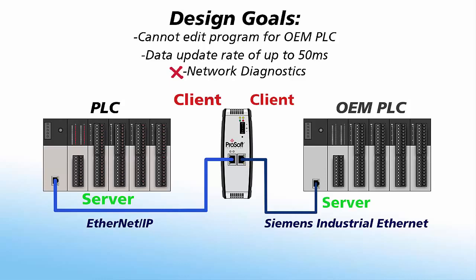The solution that meets all the application requirements would be to set up I/O messaging between the Ethernet IP PLC and our gateway. When PLCs do I/O messaging, sometimes called an I/O connection, they require a communication update interval to be set. This will ensure the communications between the PLC and gateway are fast and consistent, as they will be given priority over other communications. The PLC will also have access to communication diagnostic tags, which allow you to use your PLC programming software to